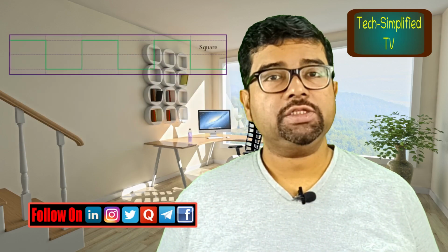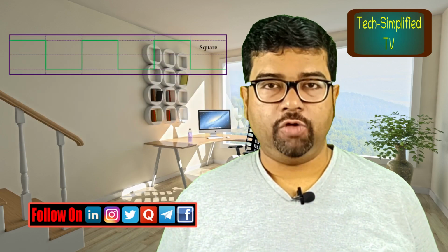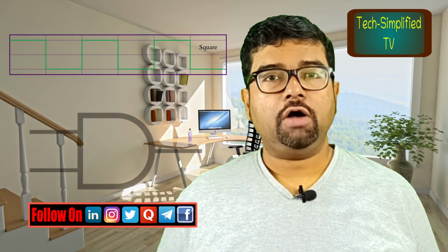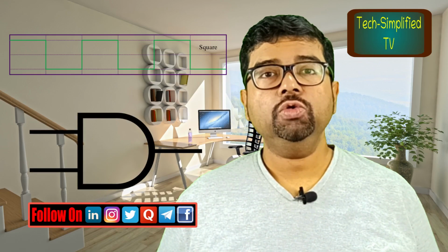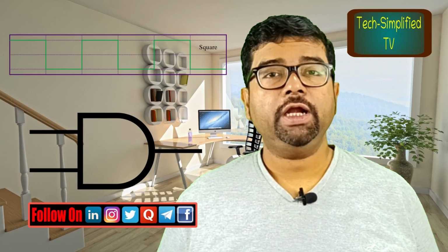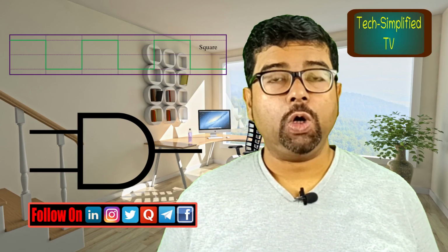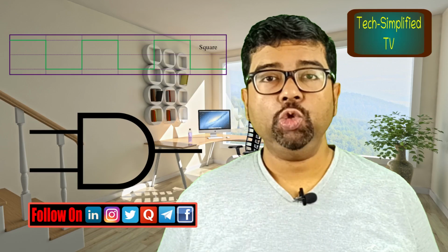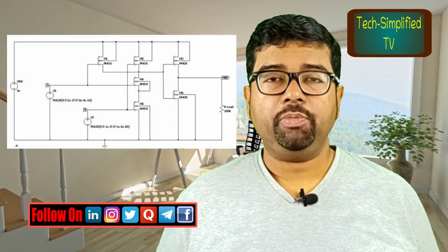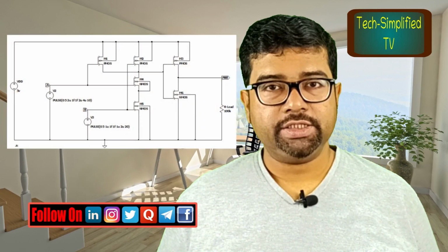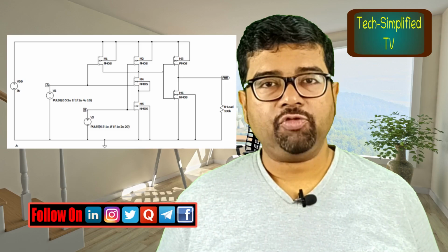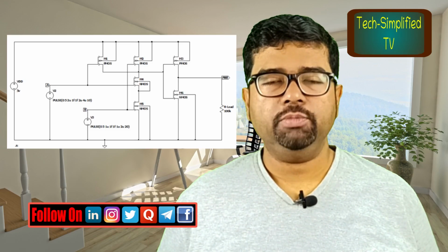We will apply pulsed waveforms shaped like square waveforms as the two inputs of the constructed AND gate. The two square waveforms have different on time and off time to cover all the truth table combinations of the two input AND gate. We will apply proper DC biasing and transient analysis to check the functionality and performance of the constructed two input AND gate.